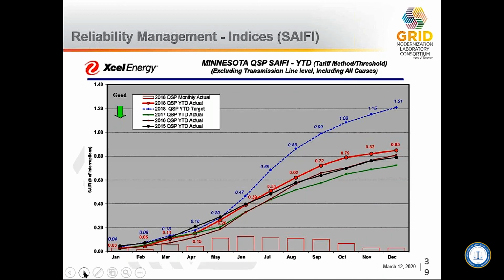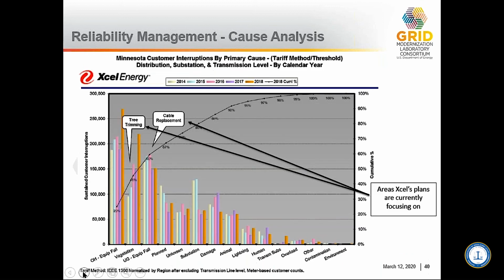And Xcel is doing this because they have a strong reliability management program that identifies the poorest performing feeders each year and does analysis to rectify those, identifies protective devices that operate often, and also identifies customers that experience multiple interruptions and perform studies to find mitigation solutions for those customers. And those solutions are ranked against the overload solutions in the budget. So this is how reliability and capacity overload projects tend to fight for some of the same money.